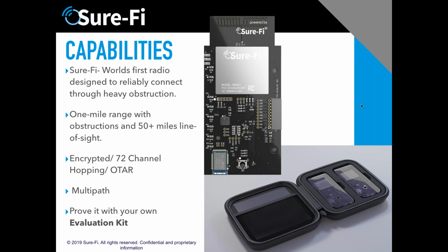For a door, yes, you can pull power from anywhere in the building, but with this new power box that we have, you can tie into the required exit signs or always-on light in the hall, and you can connect into that. It has its own backup battery, and this power box will allow you to use power right there. It has all the 12 volt DC out that you need to power everything.